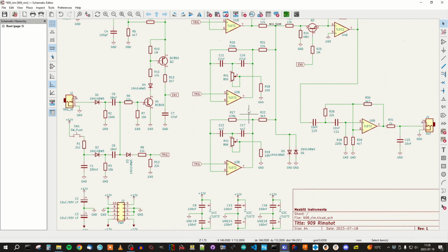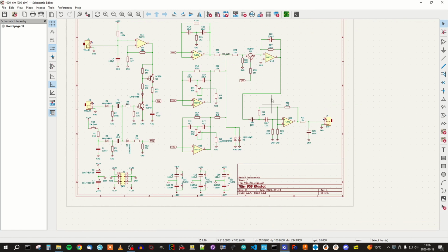Here it looks a little bit funny. So we are using, that is in the second, that is in the third. And this is totally wrong, I see. Because this is U4, we don't have power pins for that, and U5. And the reason why it became like this is because I copied this op amp 4 times. So it's used the same op amp for the rest of the design, and that is not correct.